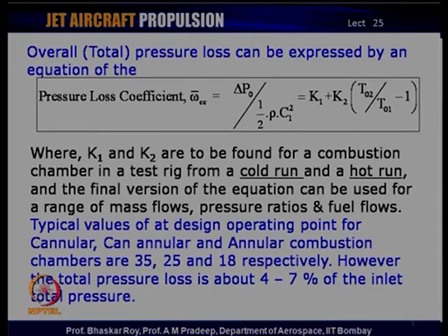It involves simulation in a test rig, it could involve computational simulation, both cold and hot, and a certain number of design variables would have to be iterated for, and it depends on what kind of combustion chamber you have, whether annular, can type or cannular. So, these are the various issues that would come into the picture to keep the total pressure loss across the combustion chamber to the minimum.